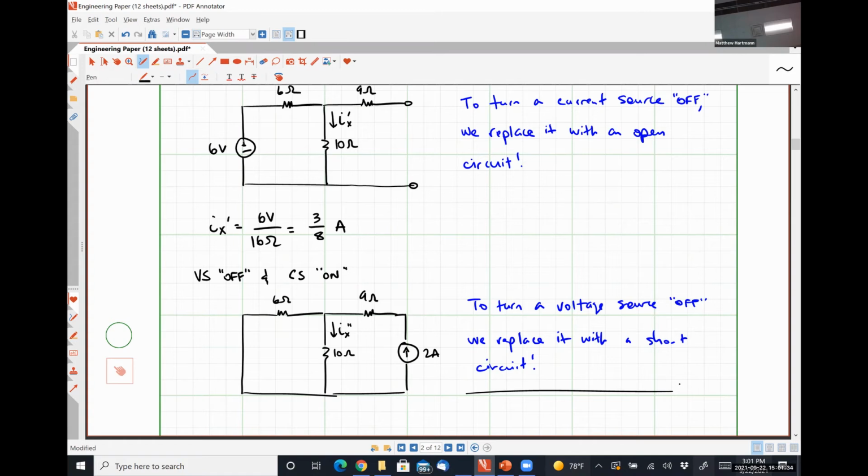So that's a fantastic question. If there is a circuit that you have with multiple voltage sources present, you can turn each voltage source off one at a time and analyze the circuit that way. Or you could do a configuration where a couple of voltage sources are on and the others off, as long as each source is on only once, you're good to go.